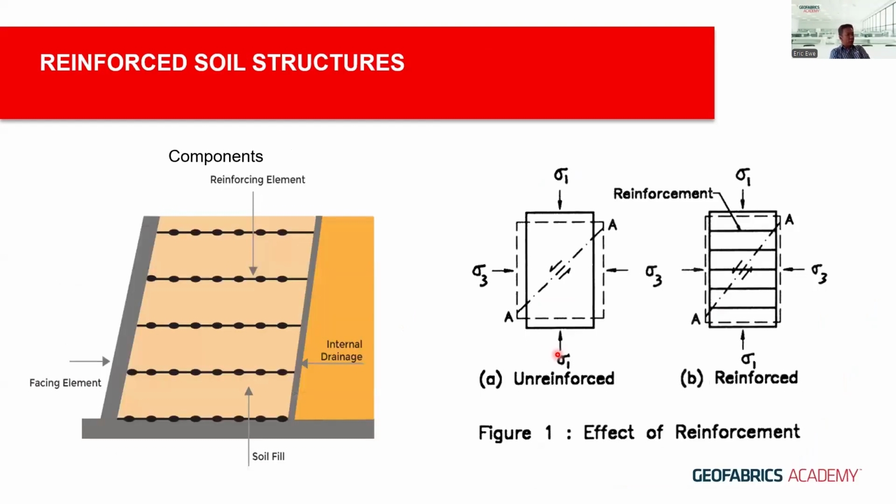So before we talk about some case history on slip repair, let's talk a little bit on reinforced soil structures. If you break down a reinforced soil structure, it comes down to the components of soil reinforcement element, i.e. the geogrid, and then the face element where the geogrid is connected to or in association with, and then the soil and internal drainage.